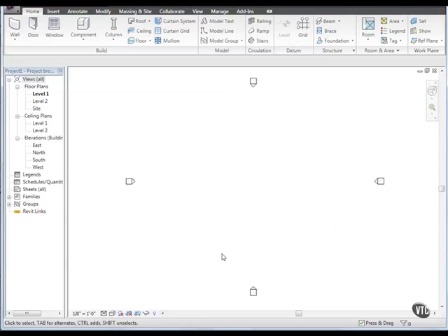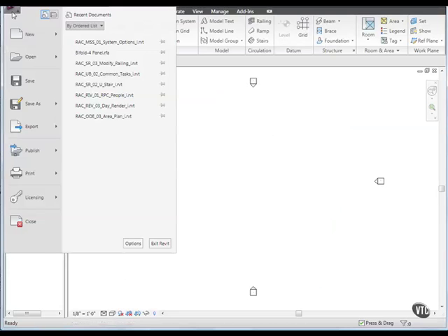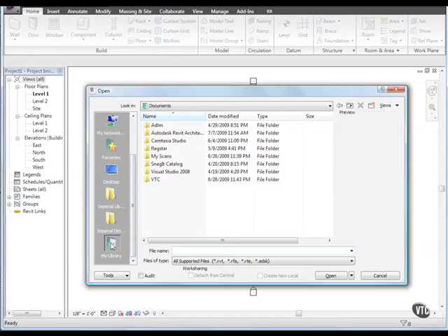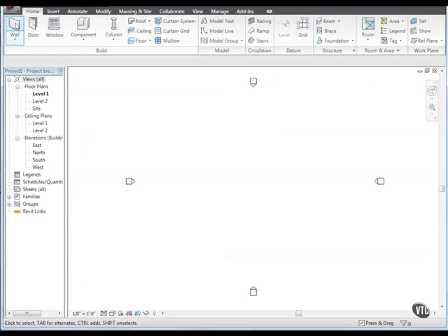and then click the menu Browser and select Open. In the left pane of the Open dialog, click the My Library icon. Notice that Revit architecture navigates directly to the library path. If you work in a large office, you may want to set up an office library on a network path to increase productivity and maintain office standards. Click Cancel. Then go back to the Options dialog box.